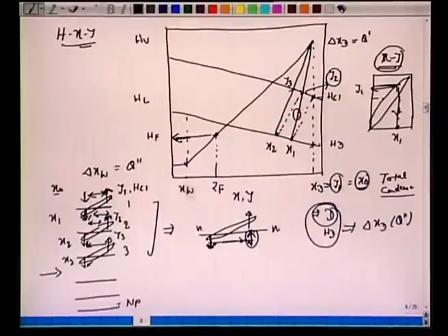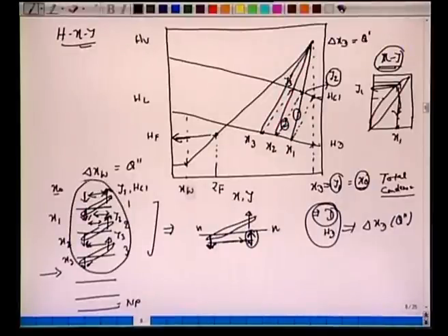So we mark that point, and whatever we connect here, the solid lines, these are now operating lines, and the dotted lines, these are now stages. So number of stages 2. It marks here Y3. Again we have to come back to this, see where it is Y3. Corresponding to this we get X3. We connect with this, we get the next operating line. So whatever is happening physically on these stages must also happen on this graph here. The dotted line connects the two leaving streams, and the operating line, the solid line, passes through this common point.